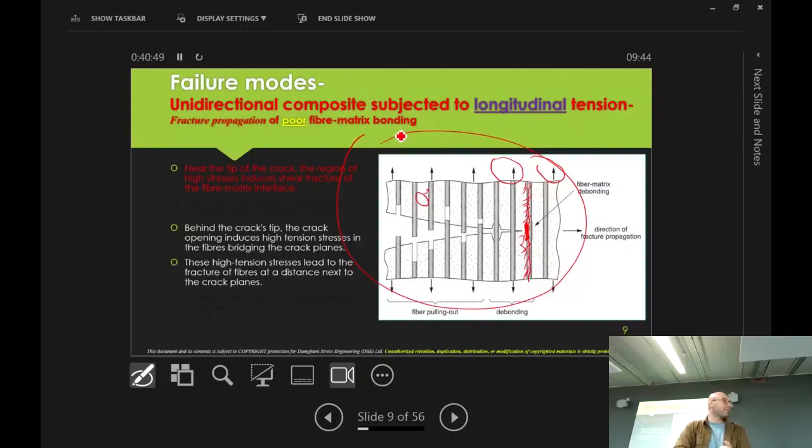There are some machine vision techniques where we look at the composite to see how aligned the plies are. Are they really 45? Because it's possible you might get 43, not 45. You didn't account for any of that. Of course, we use a big safety factor when we design things, just to account for these unknowns, which doesn't exist when you deal with metallics.